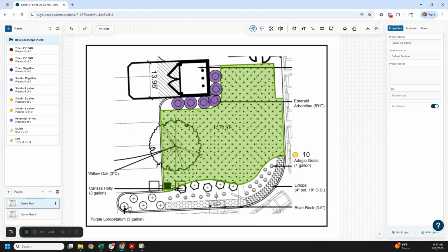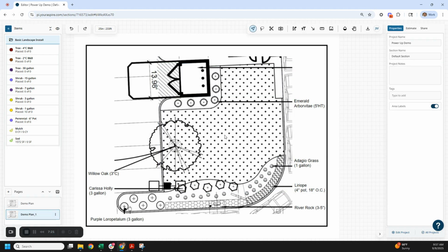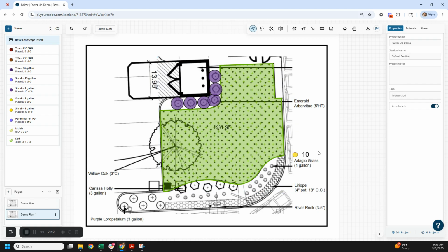So in order to do the copy and paste, I would do Control A. Control A is going to select all the drawings that are on the page. Next, I can hit Control C. Control C is going to copy each one of those drawings. Then I can head over to my other page. And now I can center up and paste it. When you hit Control V, it's going to paste it on the center point of the mouse. So Control V, as in Victor, will paste all those drawings on this page. While they're selected, I can simply move them around to line it up to make sure everything is correct. And then you can see how doing this, if this plan were changed in some way, I could quickly spot the changes that may exist on this page.